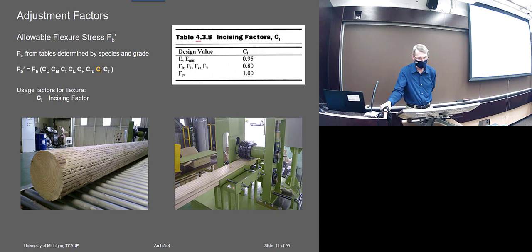Yeah, you can imagine that when you cut the wood like this, the reason they're doing it is so that you can impregnate the chemical to preserve it. And if the wood is dense, it doesn't just soak it up. If it's a soft pine, it's going to soak up like a sponge. You don't need to do too much. But if it's a harder wood, even a denser fir or a pine, then they'll incise it like this so that the chemical impregnates it a little bit better. But in doing that, it obviously cuts the fibers on the outside, so it weakens it a bit. So this cuts it down.